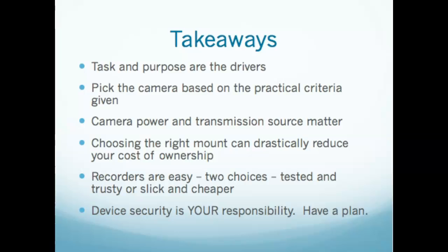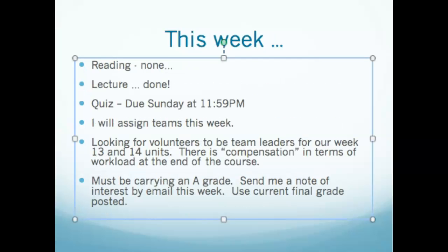Think about your power and your transmission source. Is it wired? Is it wireless? Are you using power over Ethernet, or are you going to run power to it? And are you going to plug it in, or are you going to hardwire it? The answer should always be hardwire if you can do that. You have two choices on the recorders: the tested and trusty, as I call it, with the NVR, or the slick and cheaper with the cloud. But in the long run, I don't know that it's going to be cheaper. But it is the way of the future, so think about that. And then also think about device security being your responsibility. Have a plan for that in your contracts with your camera provider. That's it for this week. So this week ahead, you have reading.